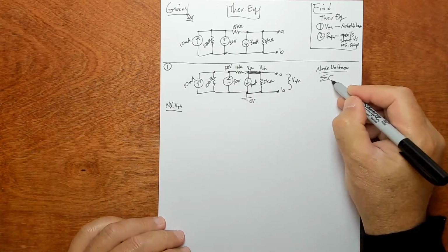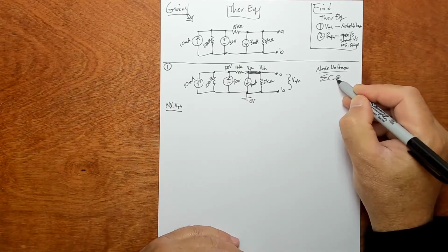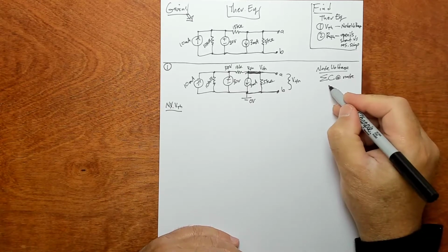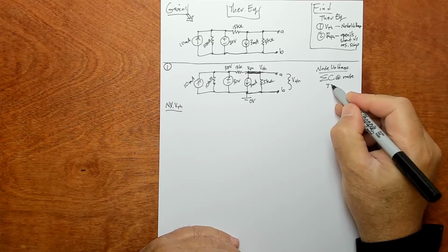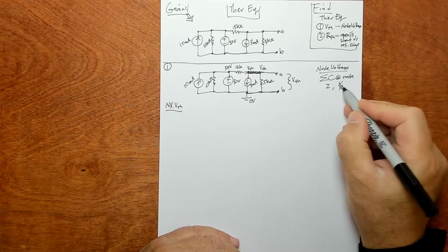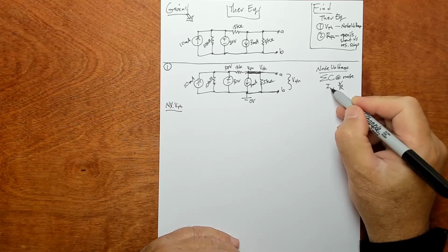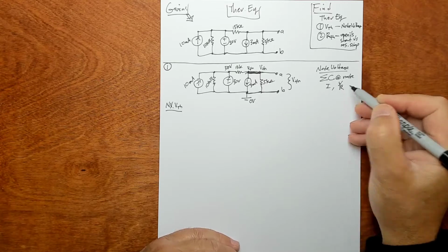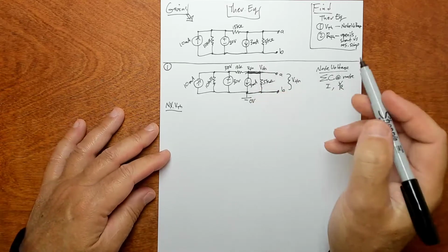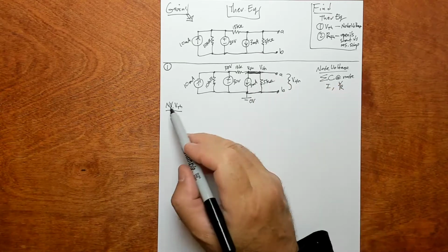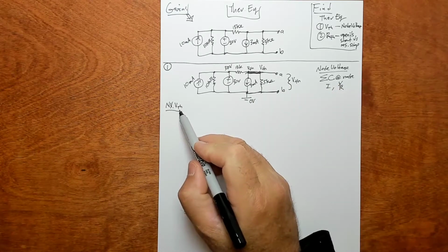We're summing the currents at a node. The terms are going to be I terms and V over R terms. The current terms that we sum are sometimes direct I terms, and sometimes, by Ohm's law, V over R terms. So let's write a node voltage for the V-Thevenin node just to see what happens.